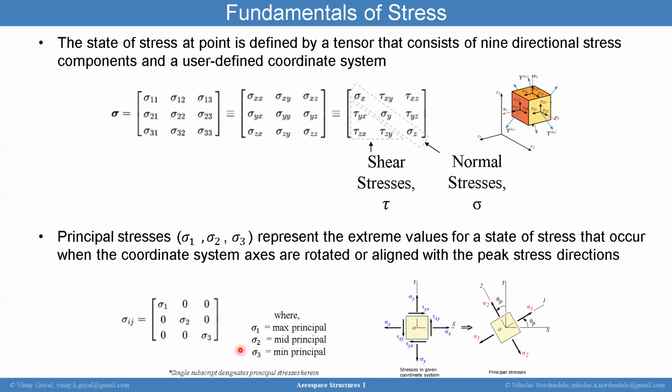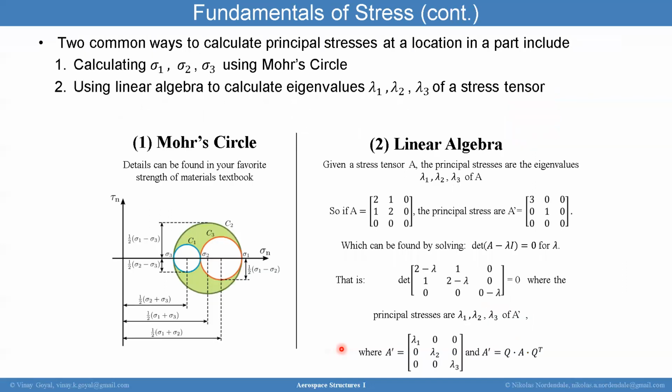And so these principal stresses play a role in the failure criteria, right? Yeah, exactly. And something we'll get into in some of the later slides is that oftentimes some engineers in practice can fall into a habit of always looking at a single stress metric to try and predict failure, whether it's a principal stress, von Mises stress, or shear stress. And ultimately, the answer isn't always straightforward. It's up to the engineer to understand the physics of the problem you're considering, what the environments are, the load types, things of that nature, to understand what the appropriate stress metric is for determining failure, which we'll show in a later slide.